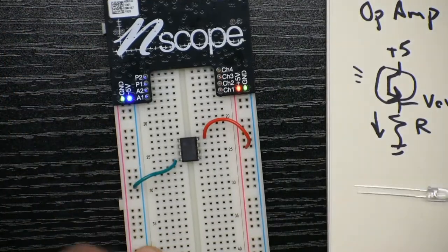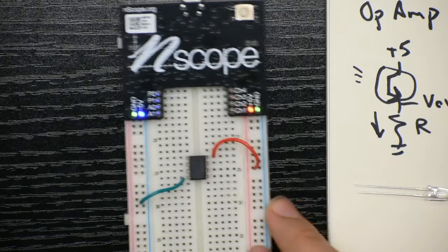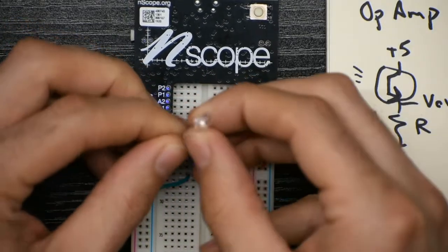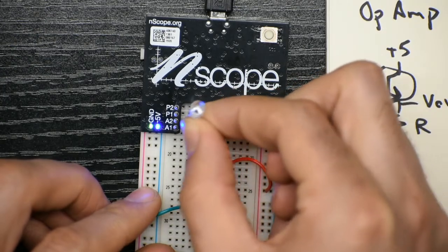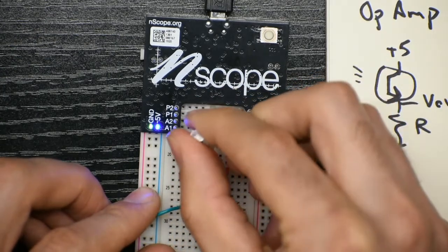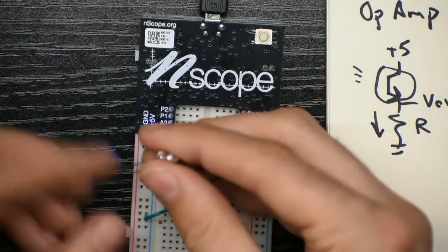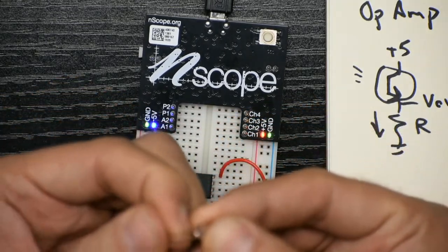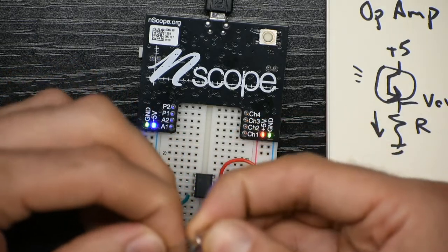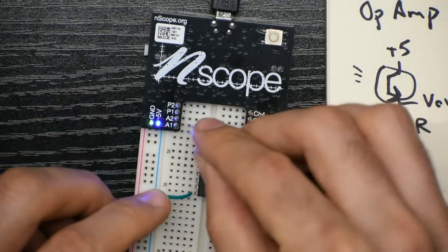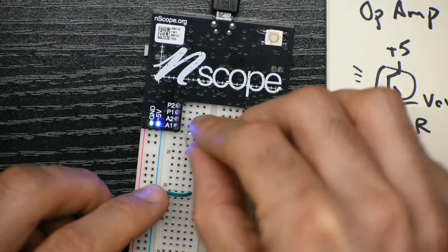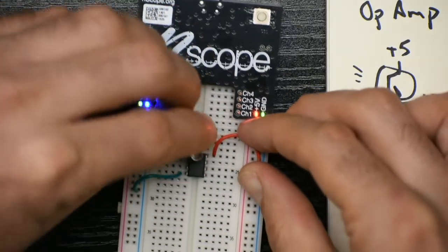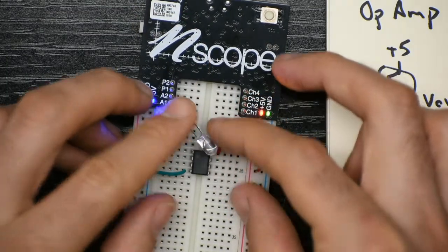And now, how do you actually make the LED and the phototransistor point at each other? You literally will have to bend them. So here's the LED. I don't want to just plug it into A1 and somewhere in my breadboard. I need to bend it. So I'm going to grab it around halfway and bend it to 90 degrees. And remember, the long side is positive. So I'm going to put the long side in A1 and the other side in some row. And I'm going to point that in some direction.